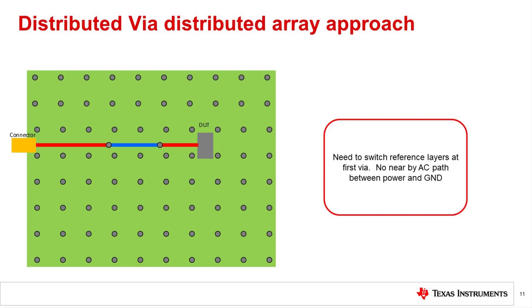One approach to connect internal ground planes together and also connecting top and bottom fill to ground is to use a distributed array of stitching vias. Many printed circuit board layout software programs provide an automatic method for creating this distributed array. The spacing between the vias can be set to be 1/10 of the wavelength for the maximum applied frequency.